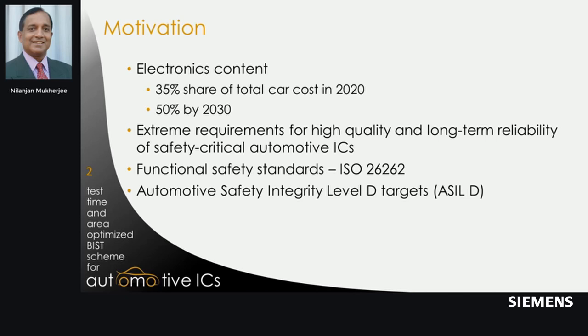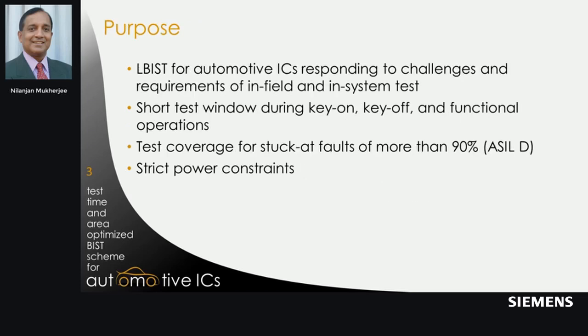All automotive-related electronic systems are governed by functional safety standards such as ISO 26262. Additionally, automotive ICs need to be certified to various safety levels, also known as ASIL, depending on the application for which the IC is being deployed. The purpose of this paper was to present a logic BIST technique for automotive ICs to address some of the challenges that are showing up for in-system and in-field testing.